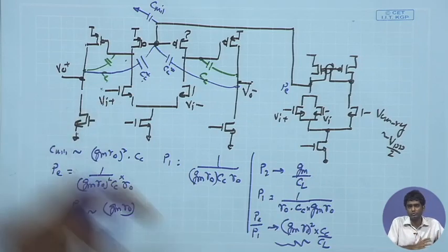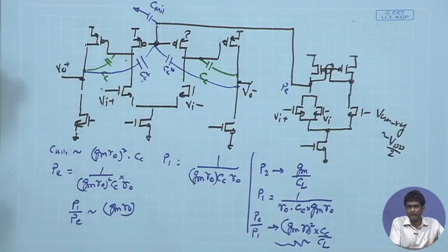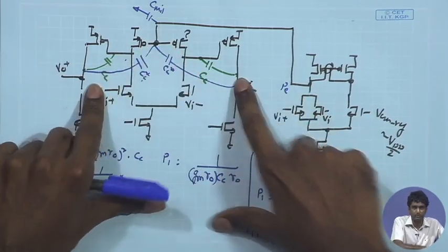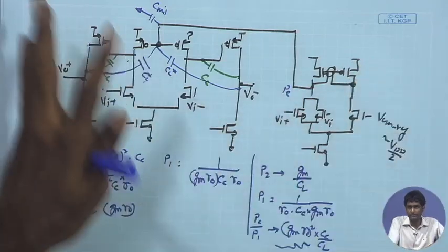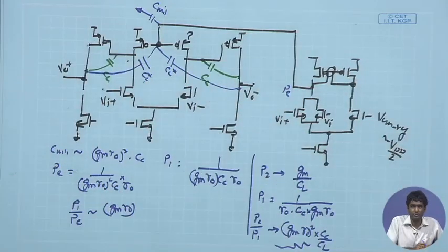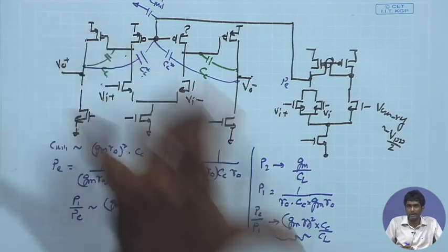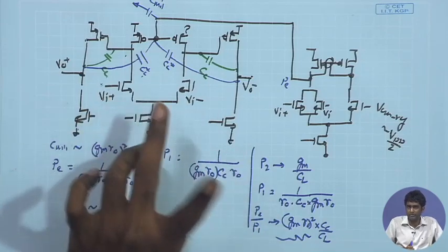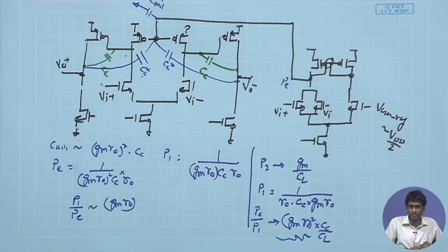So, while you are trying to solve or isolate the common mode compensation from the differential compensation with the help of this, hoping to have a better compensation for the common mode, we can see that in the overall picture you can end up messing up the stability of the common mode. So, this is another option that can come to mind if you look at where to put the capacitor for the differential and the common mode. So, for the common mode we can say that okay, hopefully we can take advantage of this one, but we are seeing some issues. This point is clear.